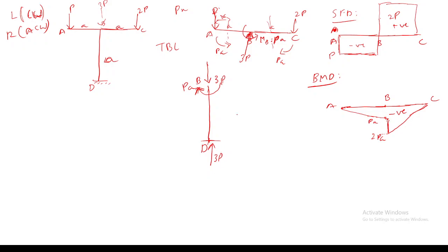Axial load. Yeah, it is an axial load, axial compressive load. And what about this PA? Due to this PA, you will be getting a moment reaction at this D, right? Opposite to this. For example, if this is towards this, then I will be getting PA. And whether this PA is a bending moment for BD or a twisting moment for BD? Bending. Yeah, it will be a bending moment.